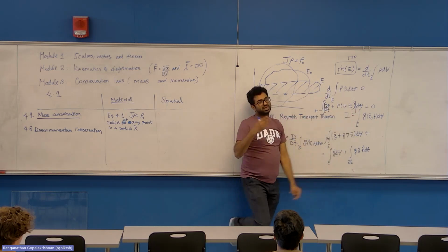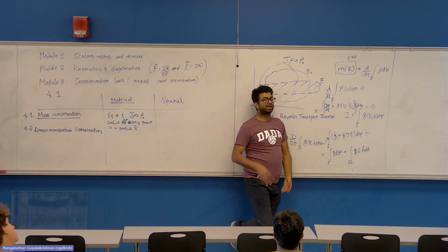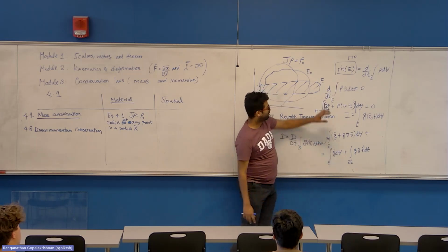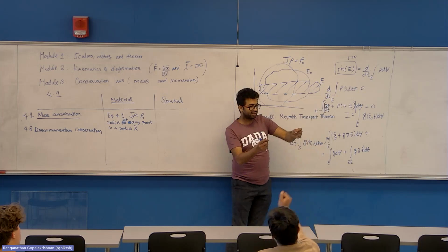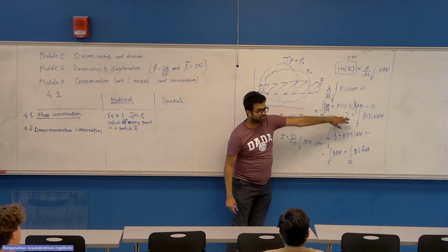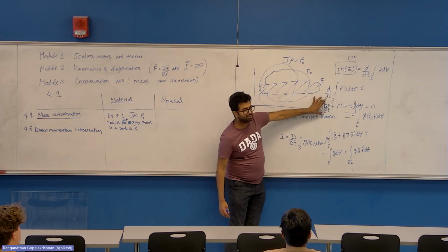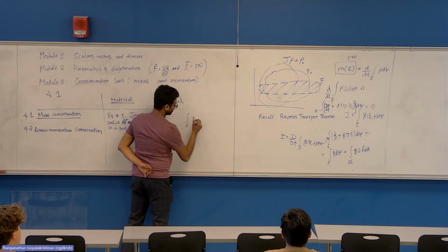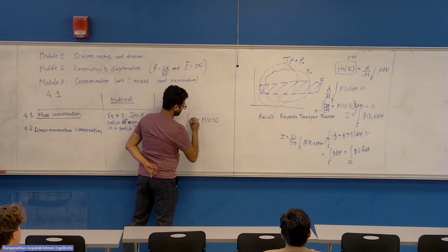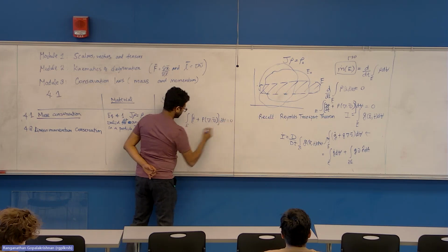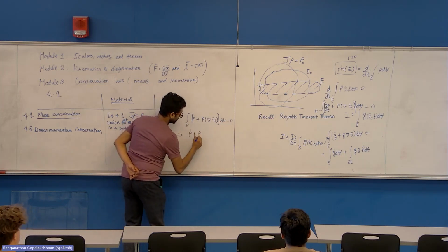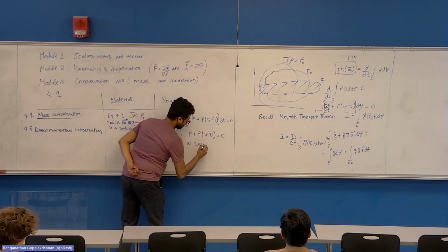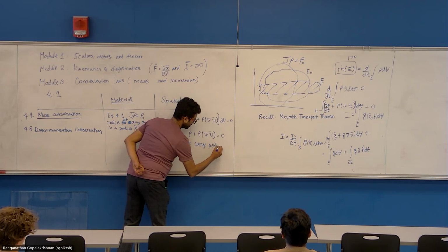Like if you say dv is dx dy dz, you are arguing let's make dv 0. That's points to you for lateral thinking. But that is a very special case. In general, if this integral has to be 0, the only way that's possible is for this function to be 0 at every point. So the integral over E of rho dot plus rho divergence of v, dV, is 0 implies rho dot plus rho divergence of v equal to 0 at every point in E.